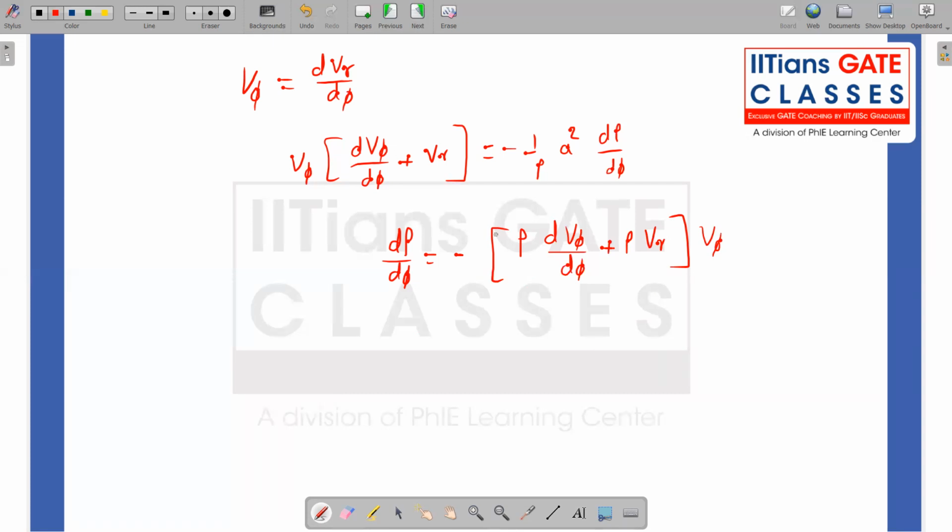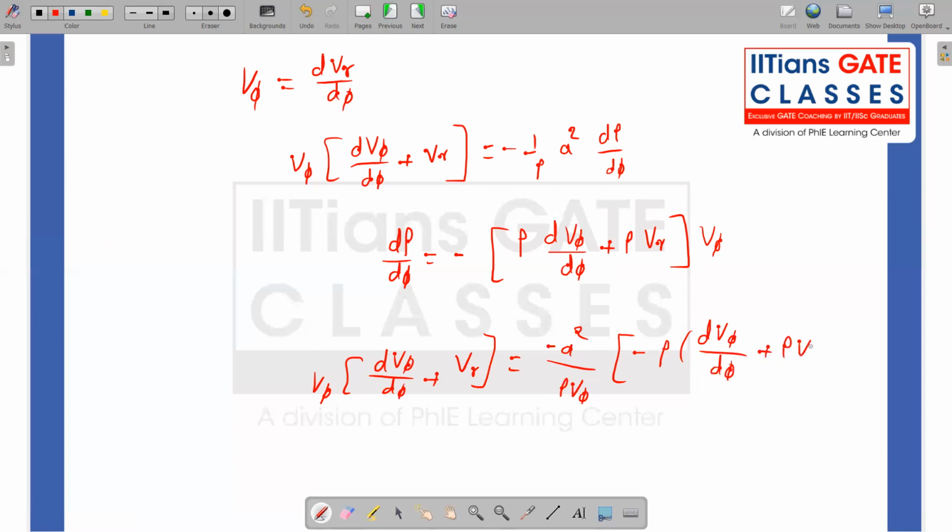So from here I have v phi times dv phi divided by d phi plus vr equal to a square minus rho v phi times minus rho times, I'm replacing this d rho by d phi in terms of these variables, dv phi divided by d phi plus rho, I already taken out, so it is just vr. So now this rho and this rho get cancelled.